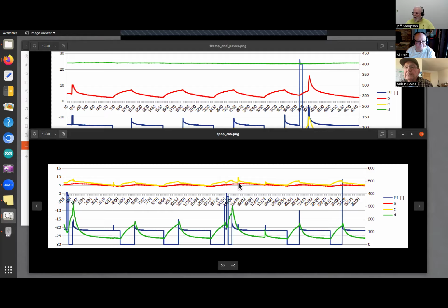And then my other problem was that I was reading both the AC power monitor and my temperature sensors with a Raspberry Pi. So I had Python code for both of those. It turns out the temperature sensors take some amount of time to convert. I looked it up, and if you're running a 12-bit conversion, which is the highest resolution you can get, it takes 750 milliseconds from the time you say start the reading until you can actually read the final value.